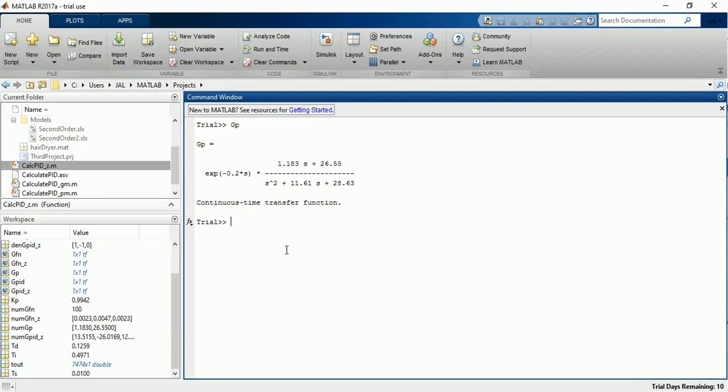And the transfer function is a second order function, as I said before, and it will be nice to see what are the stability margins of this model. We can do that by just using the instruction margin from Matlab.